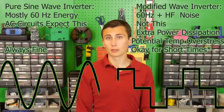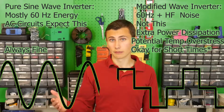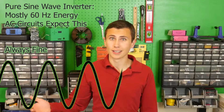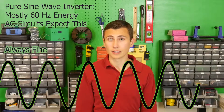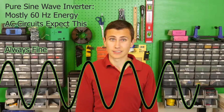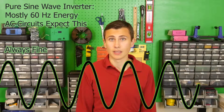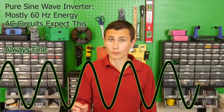If you look into any double conversion or AC to DC to AC converters, that'll supply power to the load using the inverter 100% of the time, they're all pure sine wave inverters on their outputs, and this prevents damage to the connected equipment. The short runtime 10 to 20 minute inverters can use those modified sine wave outputs, since 10 to 20 minutes of extra stress on a component is probably fine 99% of the time. That said, moving forward, I don't want to need to worry about overstressing any connected equipment. Therefore, we're going to move forward by building a pure sine wave UPS, rather than a modified sine wave UPS.